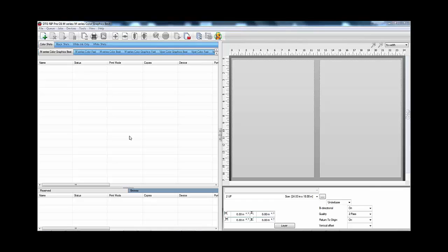The difference between the color profiles on a graphic mode is the profiles are set up to print solid colors. A lot of times we may have graphic files that, if it's a JPEG that's had any kind of compression and I have a solid red color, if I were to zoom into that raster design and look closely at the pixels, I might see that I have a wide variety of shades of red in that solid color. I'll have some lighter red pixels, some darker pixels, and what a graphic print mode does is average the color there, and does its best to print solid that color and that color only. In a photo queue or just a normal best queue, it's going to try and attempt to print every single color of every single pixel that it gets so that it can handle shading and things like that.